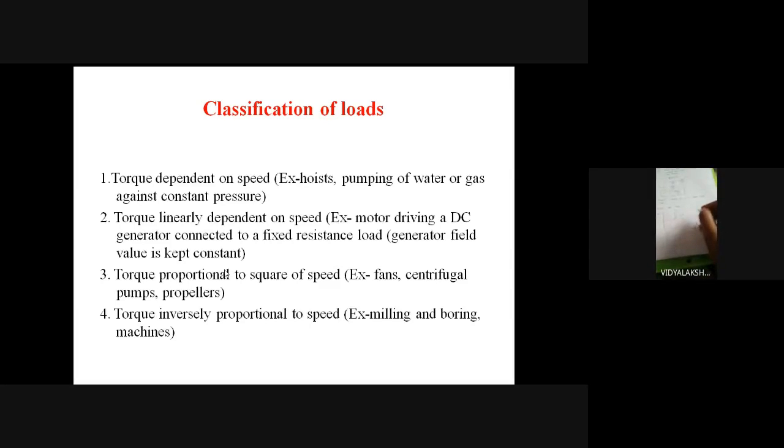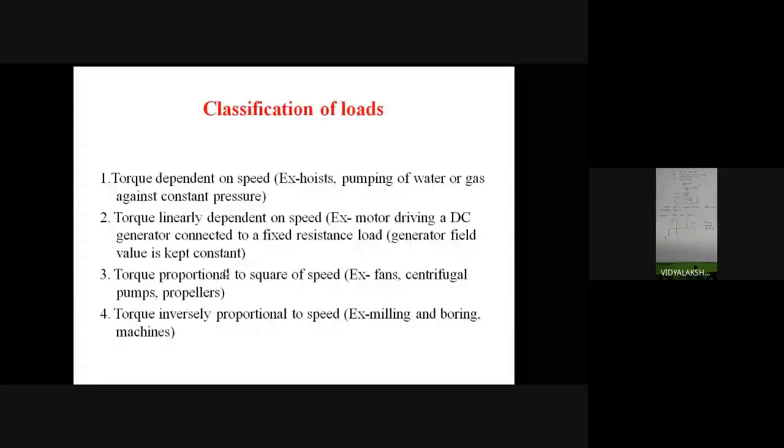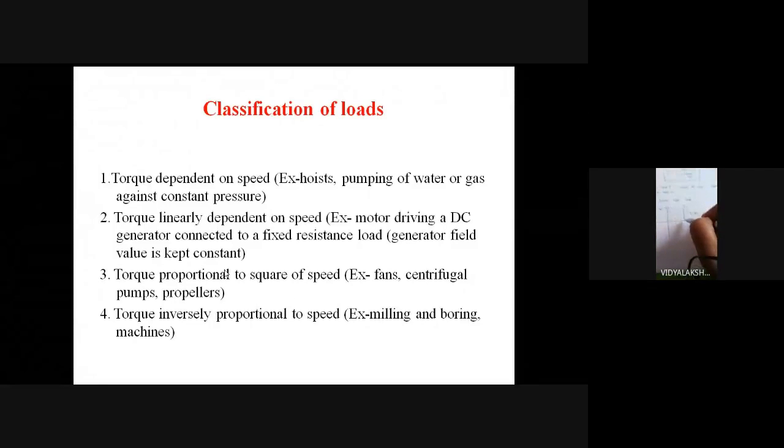Please note it down: shaping machine, cutting and grinding. There we can use this type of load. That's why I have drawn the graph like this. Whenever I'm changing the speed, I need a constant torque, so it will give a constant line.